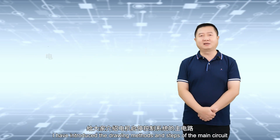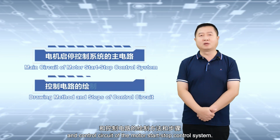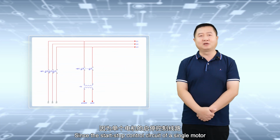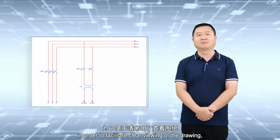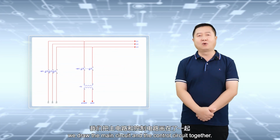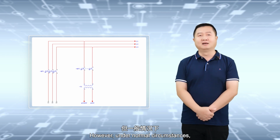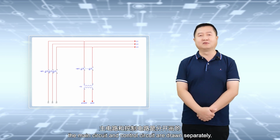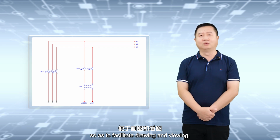In last class, I introduced the drawing methods and steps of the main circuit and control circuit of the motor start-stop control system. Since the start-stop control circuit of a single motor is relatively simple, in order to facilitate clear viewing of the drawing, we drew the main circuit and the control circuit together. However, under normal circumstances, the main circuit and control circuit are drawn separately. The main purpose is to distinguish between the primary and the secondary so as to facilitate drawing and viewing, which is also the need of engineering.